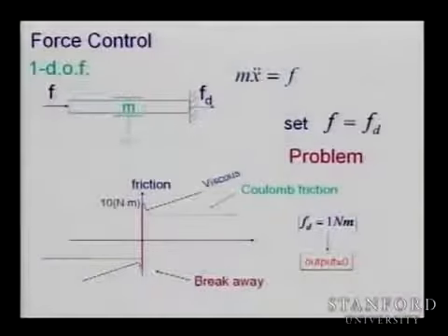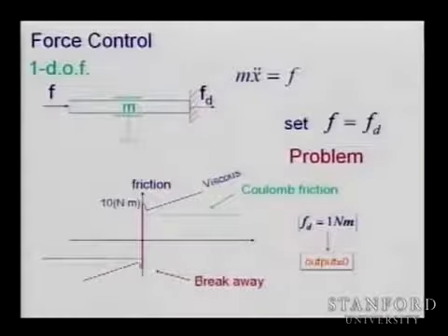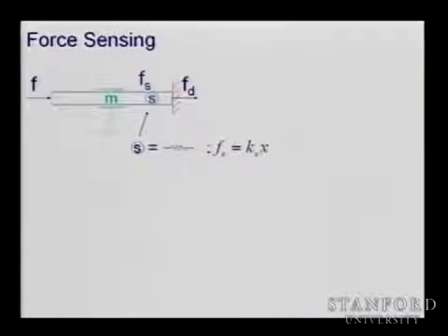All the time you are feeling those forces that are coming, so you cannot do it in open loop. So what you need to do is measure your resulting force at the output. If you apply 1 Newton meter in this case, the output will be 0. And you really need to be able to measure the actual F and form an error between your desired 1 Newton and your actual force, and then you can make feedback control. And then you will be able to do it.